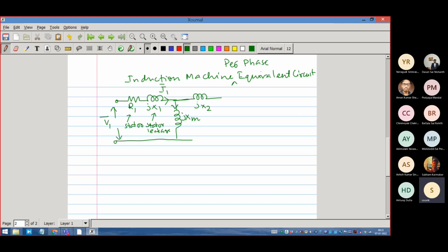So that part of this thing is here, and that part of current is magnetizing current, okay, which is responsible for creation of the effective flux, the net current. Actually, both I1 and I2 create flux in the machine. It has to, because there are 2 coils, and the stator current I1 is passing through the stator coil creating flux, and then there is a rotor current passing through the rotor coil and it would be creating flux. There is no doubt about it. The fundamentals don't go haywire.